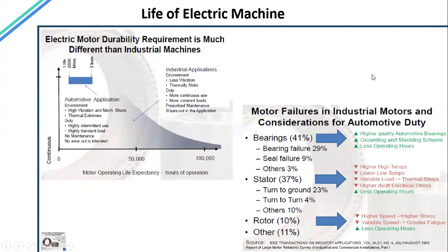So there are different fault conditions that we have to consider as well when we design, road conditions, actual life conditions, how we should recover the vehicle once it fails, whether we can tow it, because it will generate some electricity. It's a generator as well when we have permanent magnet. How we can tow it, what kind of voltage it will generate when we tow it at high speed, what are the towing conditions. Those all considerations go into machine design as well, along with the life.